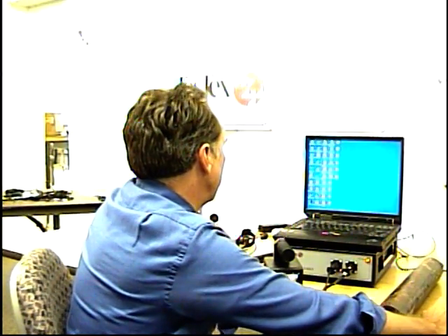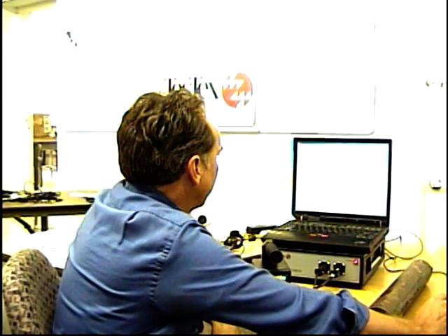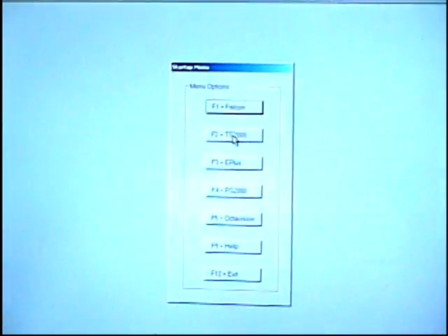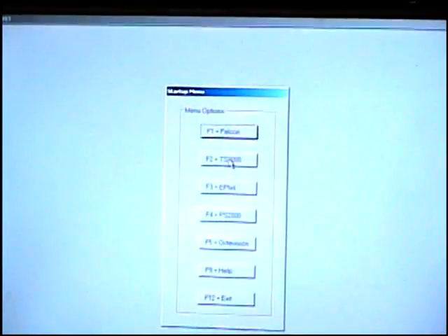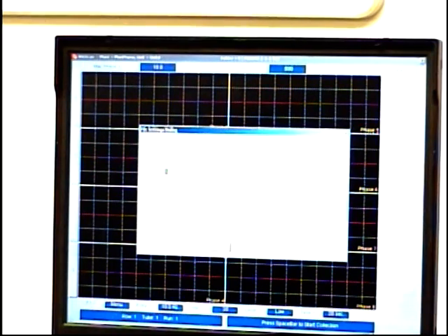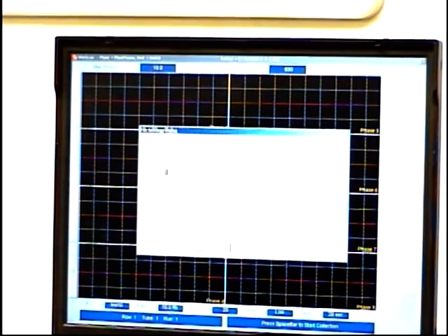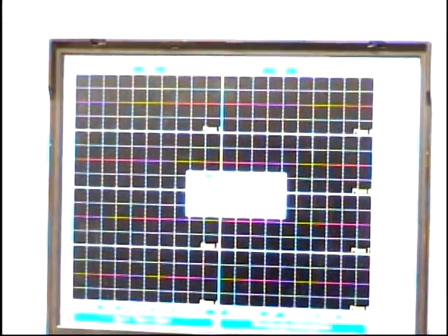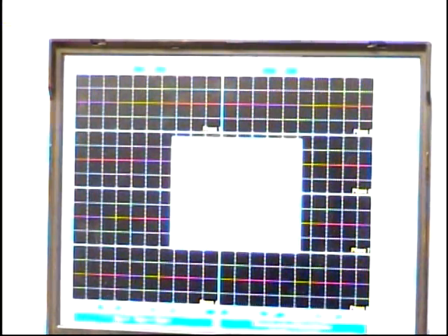Now, we're going to go into our Windows software system. Just a couple things to keep in mind: we design and make our own equipment and all software. We're going to go to F2, which is our TS2000 software, which is used for scanning on the outside of tubes. Come up to the option. You have the option for the row, the tube, and the run. The run is for if you want to do a repo on something. Obviously the row and tube are self-explanatory. There's the option for the C drive, so you can name the drive whatever you want and hit OK. I'm going to overwrite that file, but this also gives you plant information, so you can put the name, the location, the unit number.